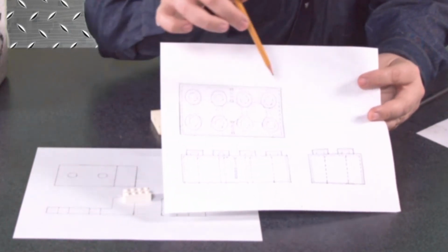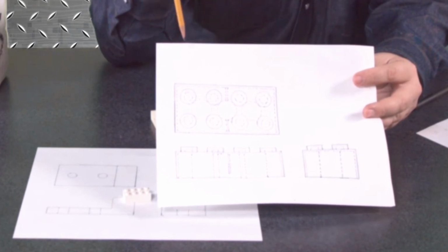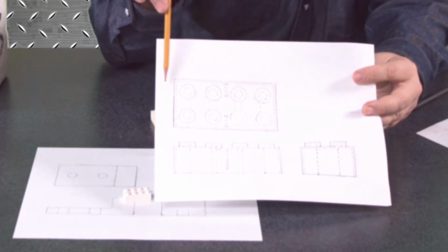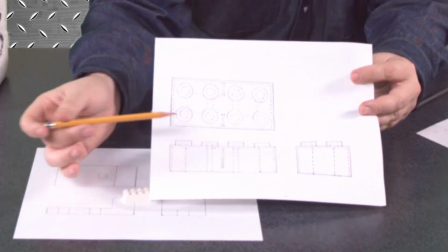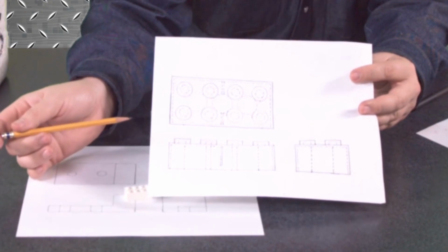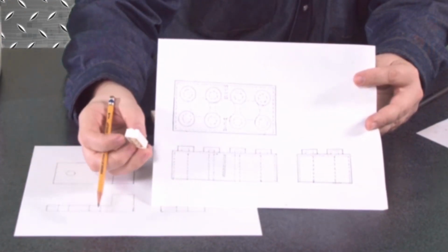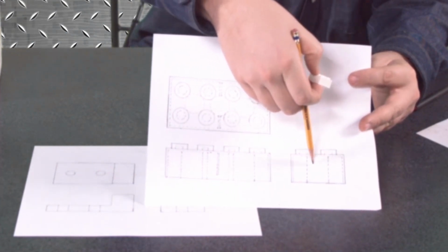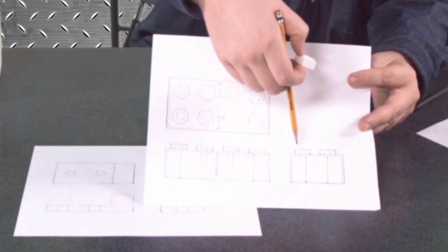If I took a cutting plane line and drew it across here and cut it out, which I probably will do later, it'd be a good show of a cutting plane and how you'd actually show the internal structure of it, and these hidden lines would switch to object lines so you could actually see what's going on inside of it. For our side view, we just turn it to our right side, and then you can see there's the 1 cylinder on the inside that we can see represented by hidden lines, and the internal walls themselves, and then